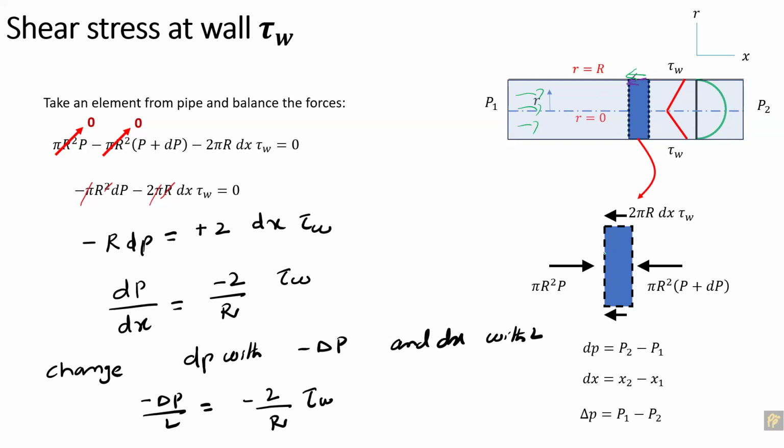So from this small strip, we have the wall shear stress, and this is only a single value. It's only along the circumference of the cylinder. These are not two values, but a single value around the whole circumference strip. So the area of the strip will be equal to, this is a dx, and this is actually a circular strip here.